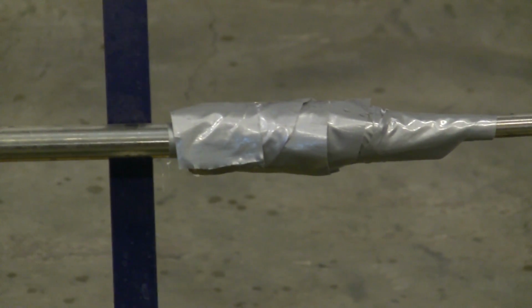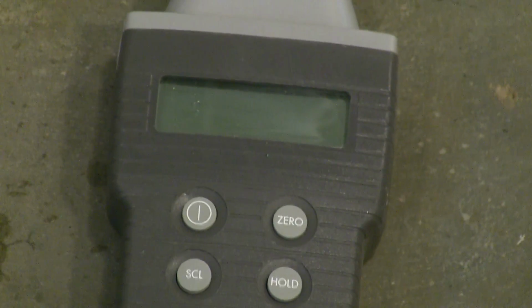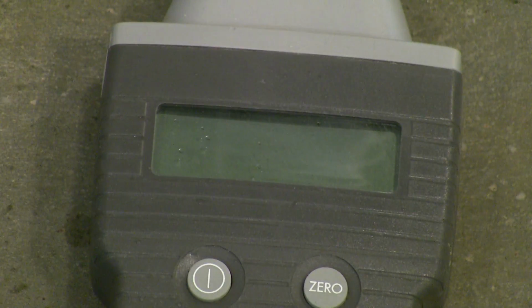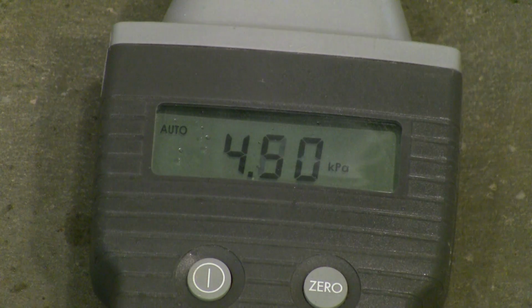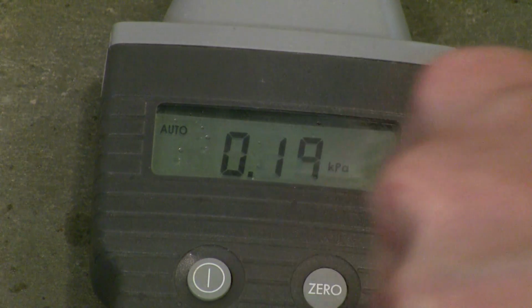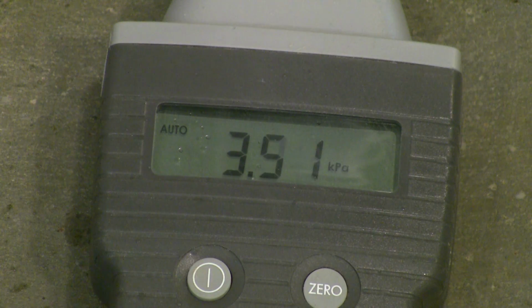Okay, so again, we're going to be characterizing the pressure drop through the 45-degree elbow. We'll move over here to the instrument. Pop it on, zero it, and begin taking some data. Instrument on. Kill the flow rate momentarily. Zero the device. It's holding at zero, more or less. All right. And we can write down several values with which to calculate our average pressure drop through the 45-degree elbow.